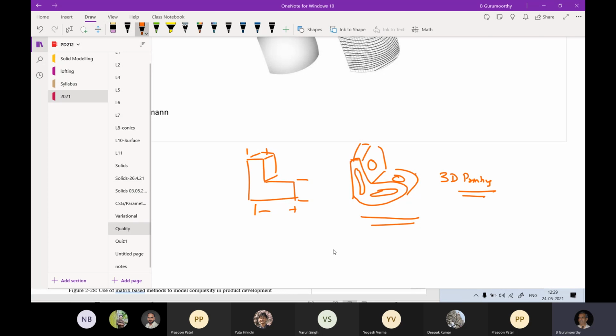So these techniques have come forward now to exploit this, because you would like to have a very high strength to weight ratio for the part. So one way is you can use materials with very high strength, but the other way, more interestingly, is to reduce the weight. And reduction of the weight is possible by using porous structures. And generative design seems to be one good way to generate these porous structures. There is a tool that has now come up which allows you to visually create these things, called Grasshopper.